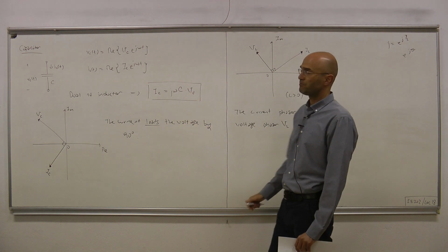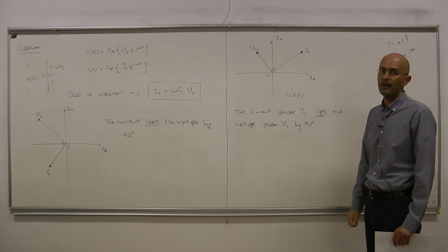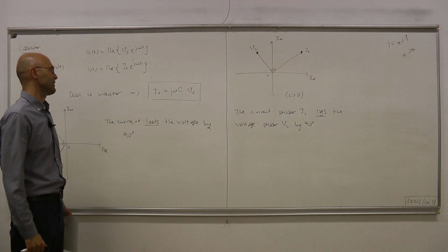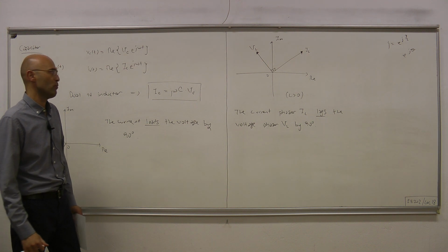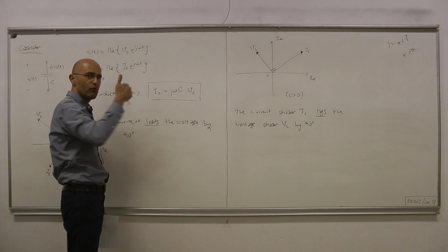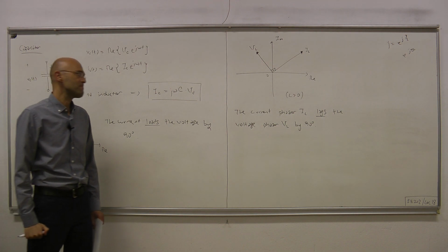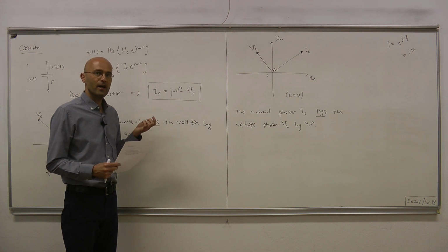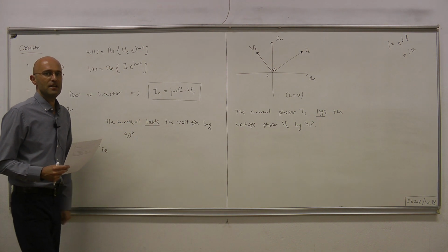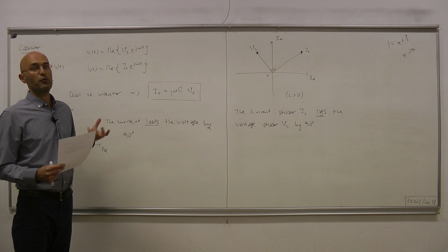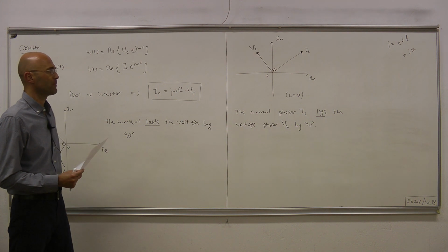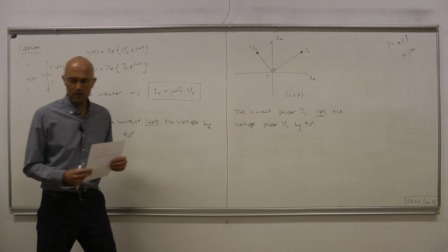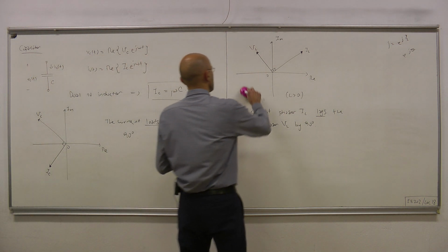Not only for capacitor and inductor, for resistor it's automatically algebraic. It directly follows from Ohm's law. So every relation for our key players, R, L, C, becomes algebraic. And that motivates us to introduce the concept of generalized resistance, which we're going to call impedance, and it's defined as follows.